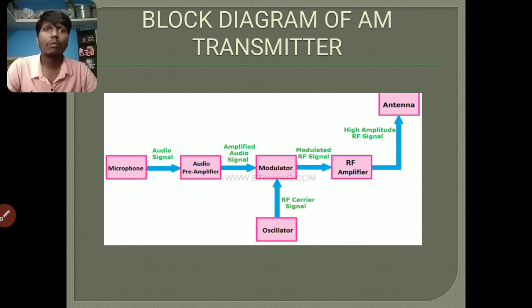Simply, we discussed the block diagram of the AM transmitter: the carrier wave is supplied by a crystal oscillator at the carrier frequency. It is followed by the tuned buffer amplifier and a radio frequency output amplifier.